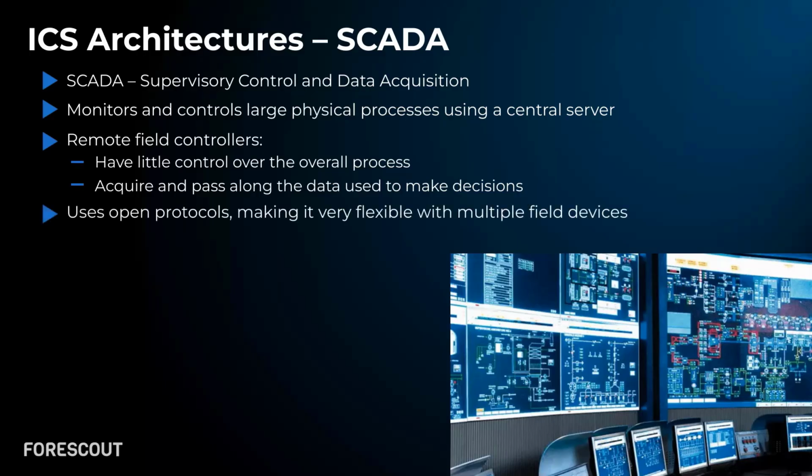In general, this architecture tends to use open protocols, which makes it very flexible when using field devices from several different vendors. The SCADA architecture is typically used in wide geographical areas, such as power transmission, or a distribution grid, which can spread throughout an entire country.